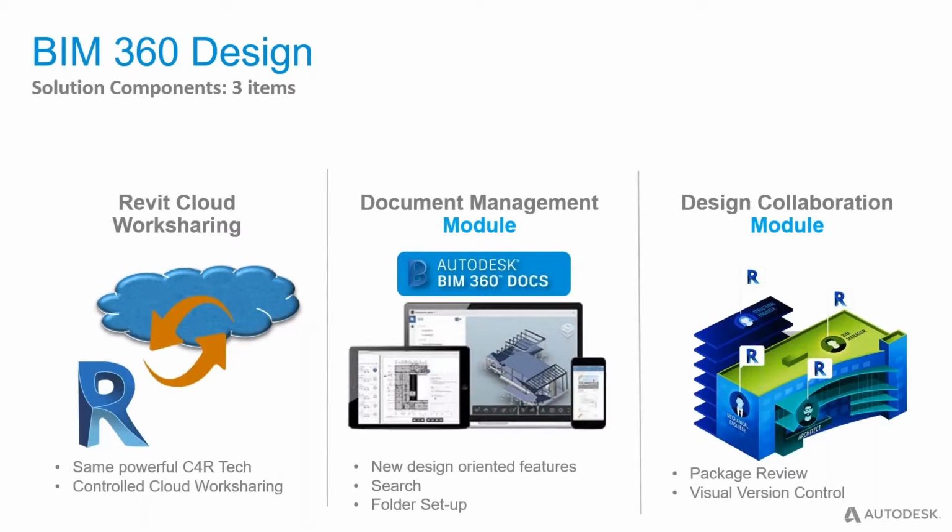That's been in Revit for, I don't know, 10 years or so. So save to central, reload latest, as I mentioned earlier on. It's actually the same buttons. The only thing we do is we push information from Revit, from the worksets, into a central model, which this time sits in the cloud. And when I say it sits in the cloud, it essentially means that we're pushing data into that base module, if you will, which is BIM 360 Docs.